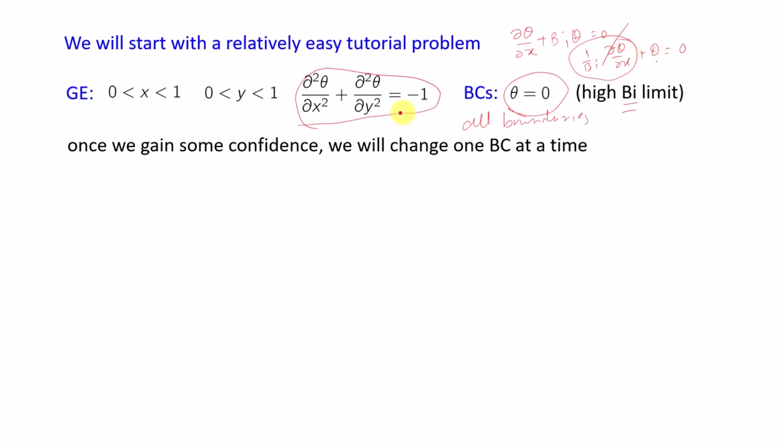It says that a lot of heat is transferred from the boundary. So the boundary temperature is pretty much equal to the outside temperature because of the high heat transfer coefficient. This is not hypothetical. This happens all the time in real applications, but it is easier to implement. Once you implement this, later on you should also be able to check your result for the actual exercise condition by simply changing the Biot number and seeing what is happening there.